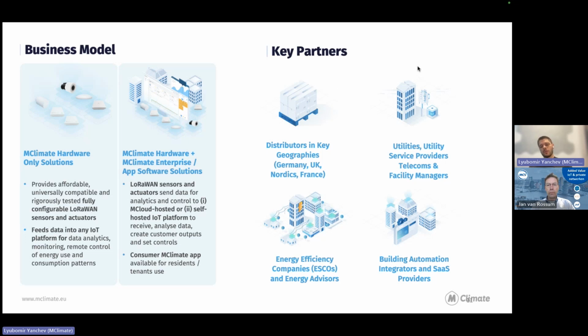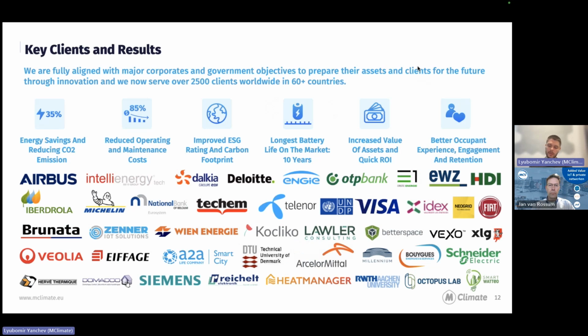And the building automation integrators, they like the products because first, they're wireless. They feature LoRaWAN, so the network itself, you don't need a ton of gateways. You need a few to cover the building, but then those gateways can route the information from the wireless sensors directly into the BMS, so they can appear like, for example, a Modbus or a KNX radiator thermostat. But in reality, you get the benefits from LoRaWAN, which is long range and very good battery life.